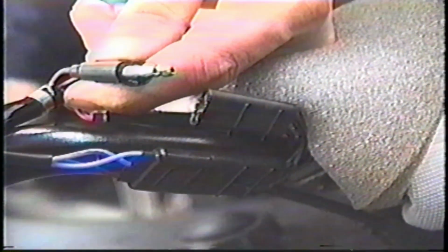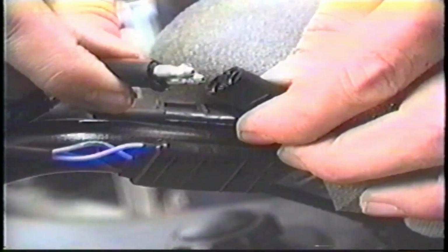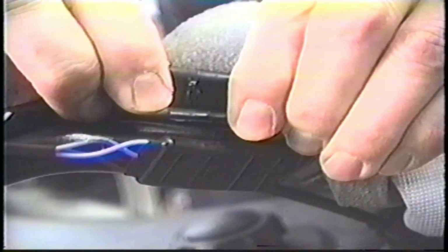Caution: under no circumstances should the machine leave the dealership with the control switches disconnected. It should only be done as a quick test. Inspect the wires and connections within the ignition system. Look for open connections, corroded connectors, or damaged wires. All connector pins must fit together tightly. They should be free of moisture and coated with Polaris dielectric grease. Check to make sure that harnesses and components are all securely fastened.